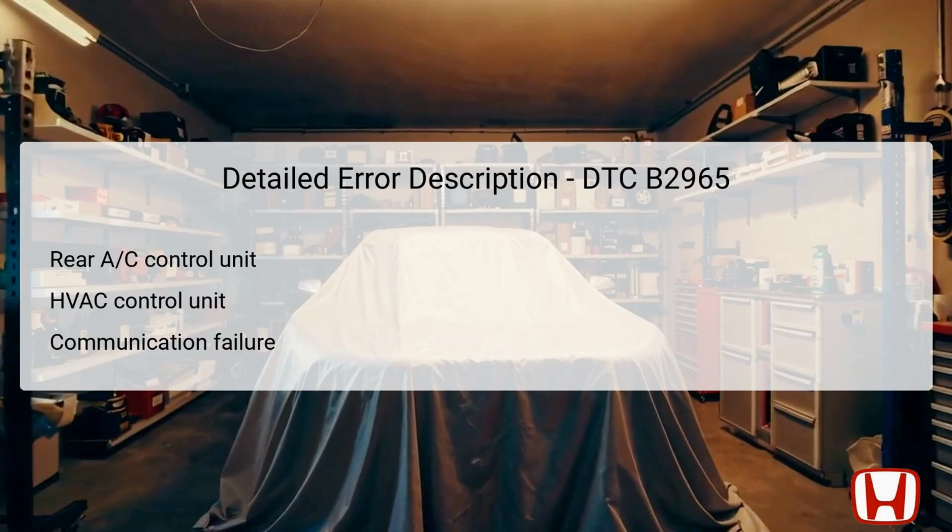If there is a breakdown in this communication, it may manifest as functional issues with the rear AC system. This fault can often be traced back to problems in the wiring or connectors that link these units. Diagnosis usually involves using the Honda Diagnostic System, HDS, to check for any logged trouble codes, which will help pinpoint the problem's source more accurately.